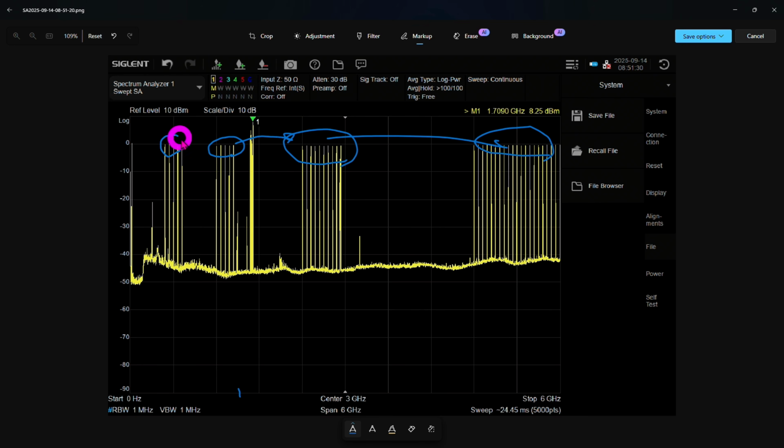And this section over here is the divided version of this, which is also working. And there's a tiny little bit here at the bottom, which is a heterodyne section. So these are all really the same thing. This should be able to go further down. And if this does go further down, then this will be able to go further down. And then these guys will all be able to go further down. So yeah, this entire range is definitely not working. And the VCO only gets locked in a small portion of its entire range. And all of these measurements are really connected to each other. So it all really actually makes sense.